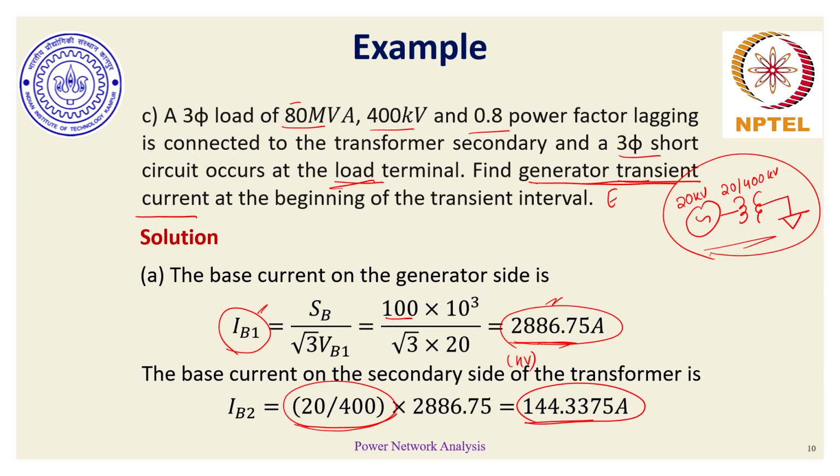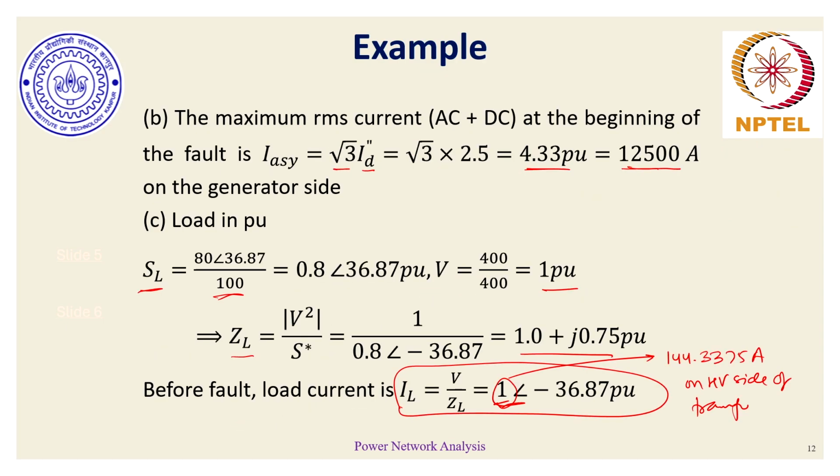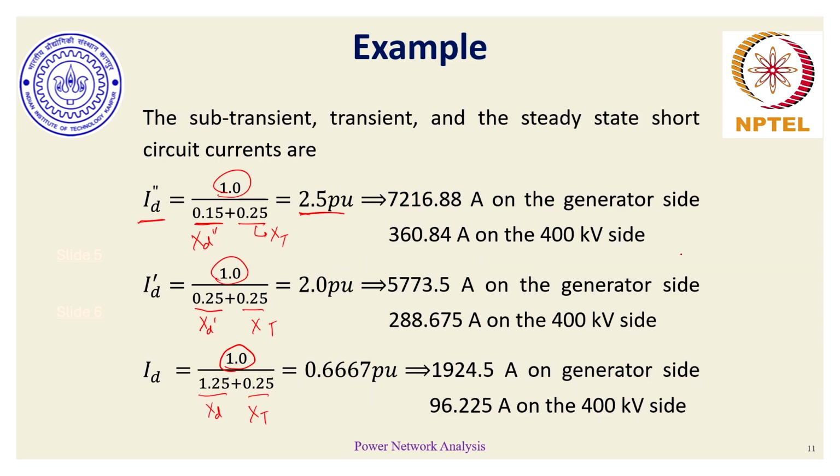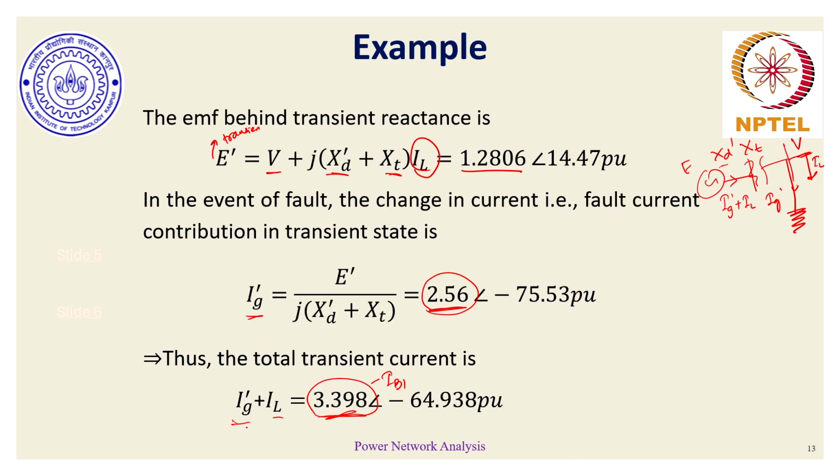It would be more than 9,000 amperes of current flowing in case the machine is loaded. So basically what we have done is superimpose the load scenario with the short circuit fault scenario discussed in this particular slide, and just added those two currents by superimposition to get the total transient current from the generator to the load as well as to the short circuit fault, which is very large compared to the normal flow of current.